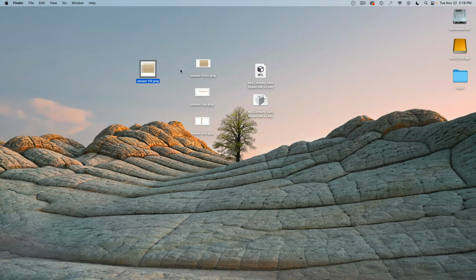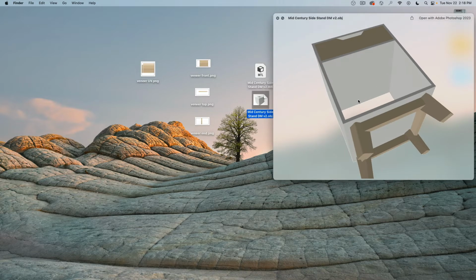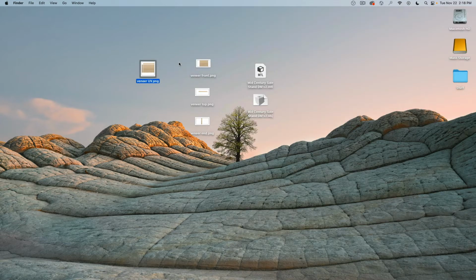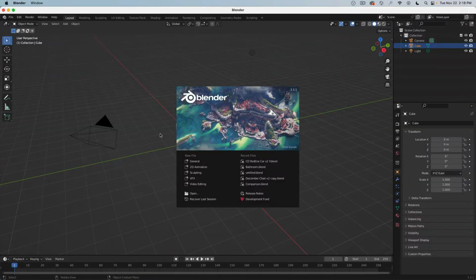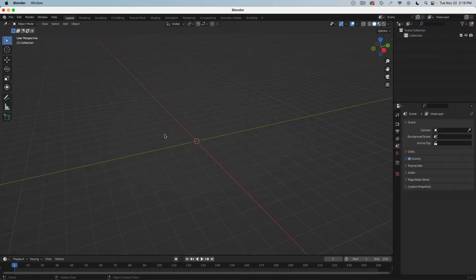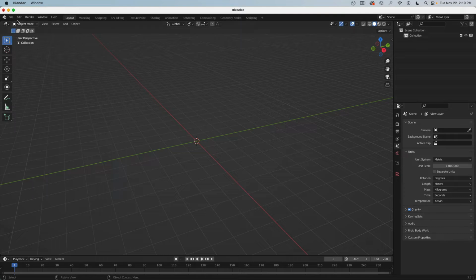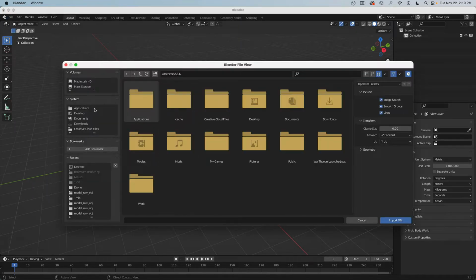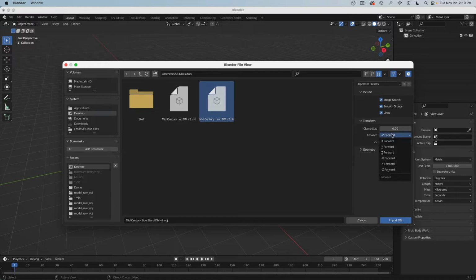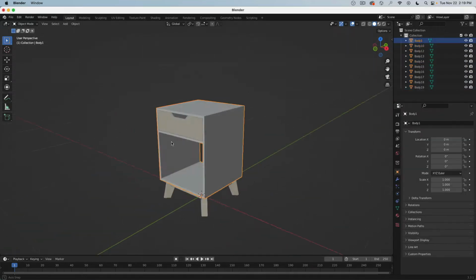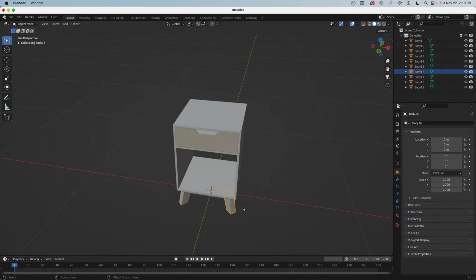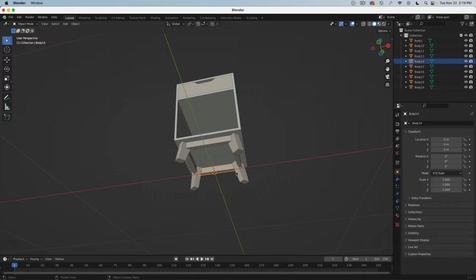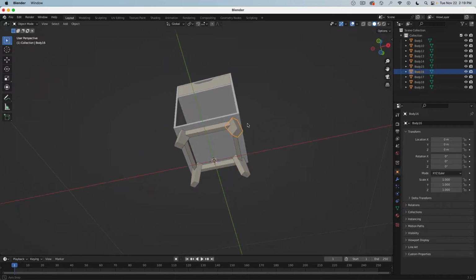And now we are ready to bring the geometry into Blender, replace the legs, texture everything, and then design the scene and render. So let's do it. In Blender now, I am pressing A, delete everything. I make sure my scene is set to meters, import OBJ. There's my OBJ, Y forward, Z up, and split by group, import. And I can zoom in, and you see here I have all the individual bodies. Beautiful.